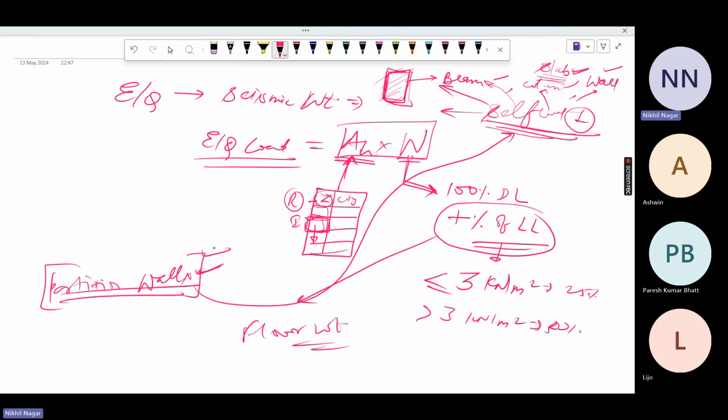That's how you assign the partition wall load in the member weight, because the program cannot see them in your model, since we didn't model the partition walls as plates. So that's how we assign it manually in member weight. Is your doubt clear? Yes.